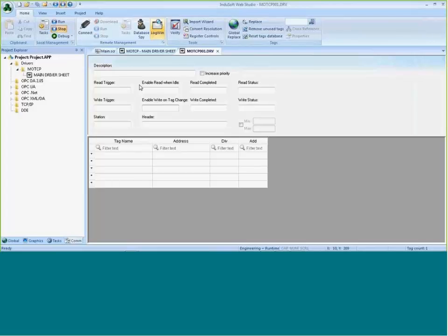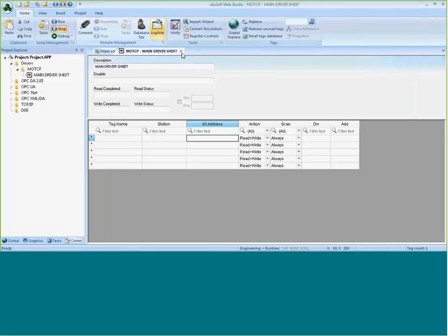Believe it or not, some customers want to go slower. For example, they may have a leased line or an expensive connection to maybe a satellite or a radio modem, where maybe they only want to communicate once a day or every hour or something. You can set that up in here and then burst communications and then shut off your radio and have everything go to sleep, and save battery power, let's say, or costly connections as well.